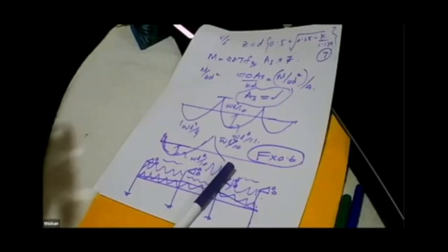If the load of the slab is distributed to beams as per yield line pattern, is it reasonable to curtail bottom reinforcement close to the corners of the slab? Actually, in two-way spanning slabs, no engineer practices this in Sri Lanka. All the moments that you calculate based on the yield line method are applicable only for the middle strips. End strips is a nominal reinforcement. By practicing the edge strip, middle strip method, you can save a lot of steel in a slab.